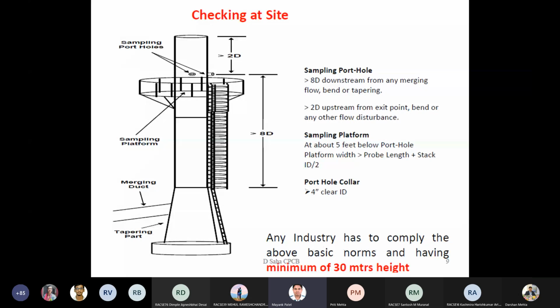And before you go with this monitoring of the stack, you need to select the pitot tube and thimble based on the condition of that stack, right, the temperature of the stack and the material of construction of the thimble. Then you will measure the thimble weight before and after this monitoring, and you will get the idea of the PM, particulate matter concentration, by substituting these values, right?